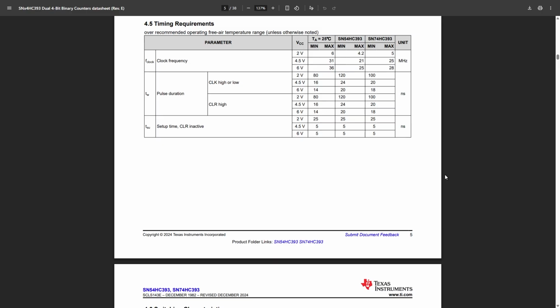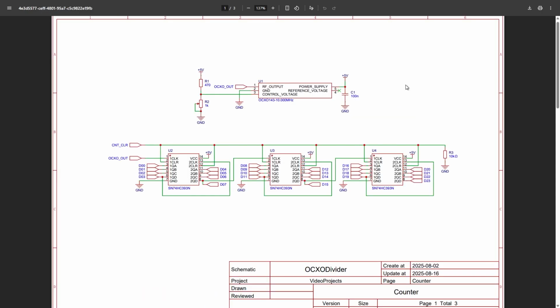We should take this information on the right as the worst case scenario, maybe when the chip is near its extreme operating temperature. And we as engineers should always prepare circuits for the worst case scenario, therefore always taking the most restricted values we see in the dataset. Although that's just my recommendation. Now that we got the counter sorted out, let's go back to the circuit.